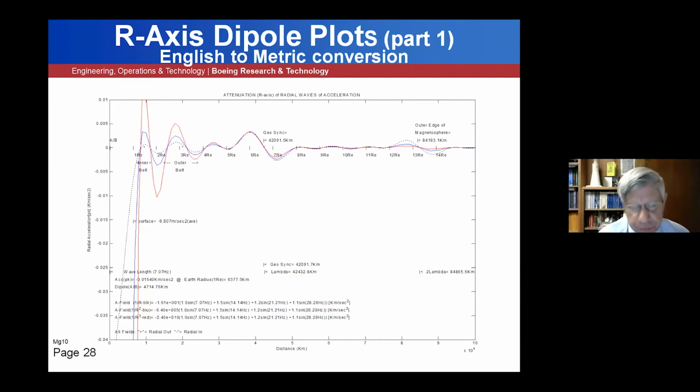Now, what I did was on that black dotted one, which is 1/r roll off for the terms, I put on the blue, which is 1/r squared, and the red is 1/r cubed. What I was trying to see was what effect the different roll-offs had on the field. Now, as you can see, it's mainly under a half a wavelength.